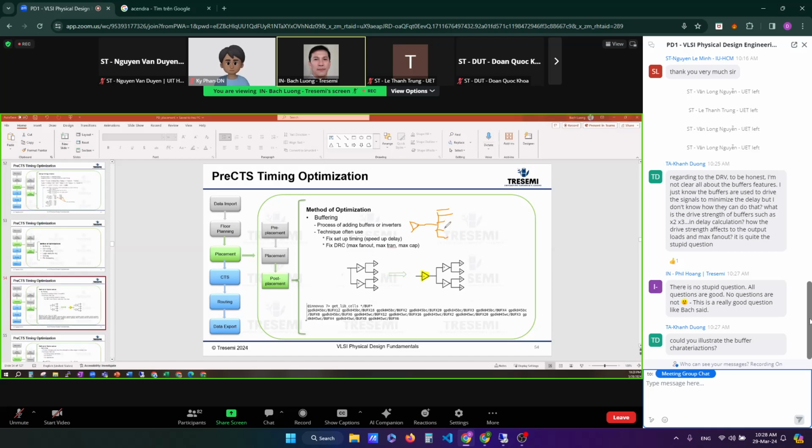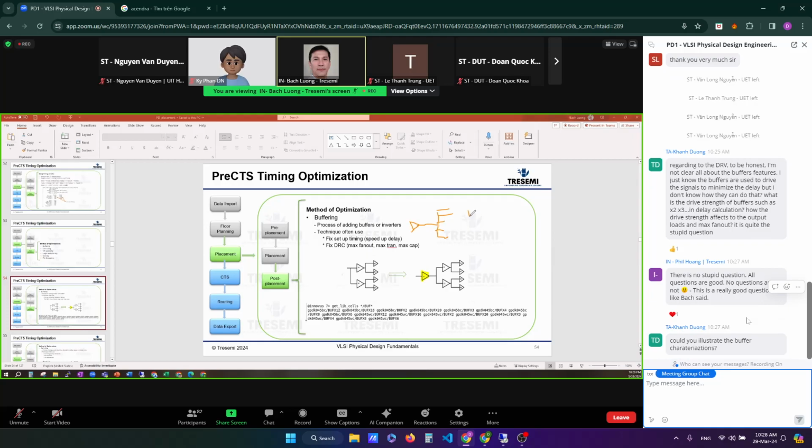This is too many, right? So you've got to add a buffer to limit the fan out of this guy. So you might just split it up to 3. Insert buffers here to break up the fan out. So that's to break up the fan out.